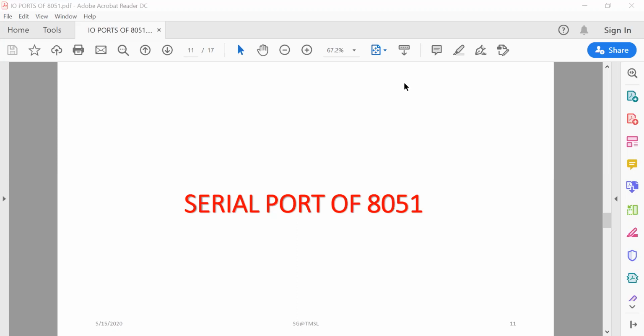In asynchronous transmission, there must be a start bit and a stop bit along with the actual data. Suppose one data is 8 bits wide: D0 to D7. First D0 will be sent, then one by one up to D7.